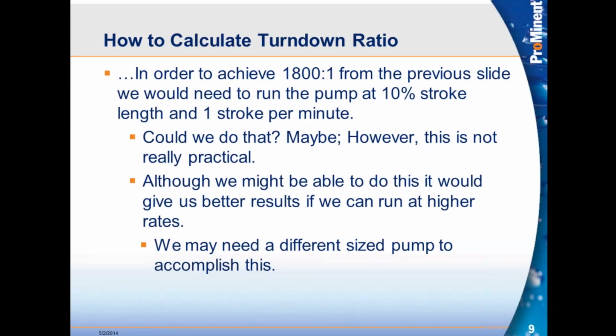So from the previous slide, we would need to set the stroke length at 10% and the strokes per minute to 1. Now, we can do that. We can physically do it. It will allow us to do it. If the hydraulic conditions of the application are correct, the pump will function. It will be repeatable. It will be accurate. But is that practical? Is that really practical for the customer's application?